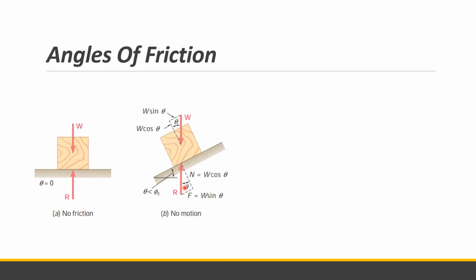Now, the board can be given any desired inclination. So, say at an inclination angle theta, which is still less than the angle of static friction. So here comes the importance, or the advantage, of angles of friction for problems on an inclined plane, where the block is in no motion, or motion impending, or about to slide down.